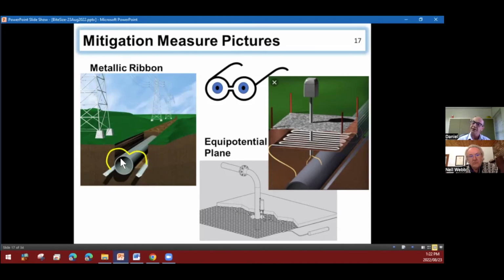The mitigation is twofold. The one is that we are reducing the voltage on the pipeline by grounding the pipe. The second part is that we have got a ground potential rise, where the ground potential also rises due to the current coming off into this bare conductor. So the two aspects then assist to mitigate the issue, to make the place safe.